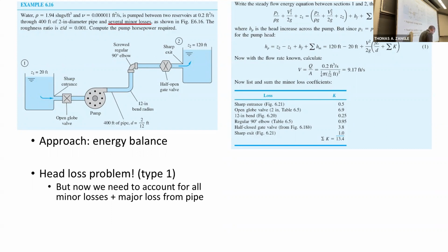And one more thing, with the length, is it the total length of your draw line? In this type of problem, we're going to assume that the length is the total length of pipe that we have, not including the fittings. So like that bend, you wouldn't have to do the geometry of how much length is in this bend. You would just assume that's negligible. So think of the length as the length of the straight pipe. That's right.